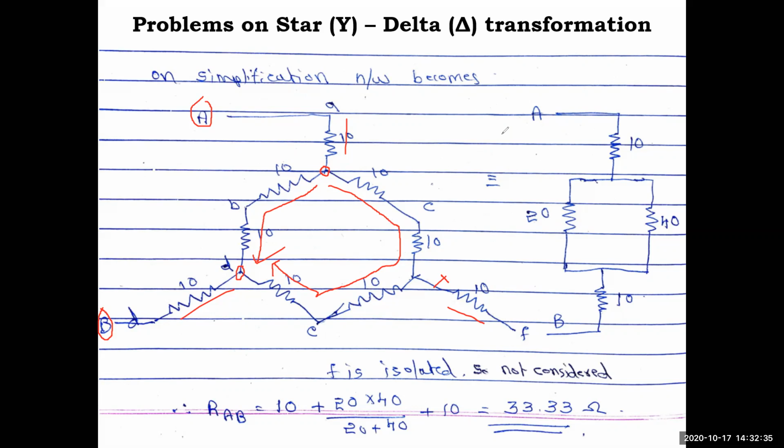So now the equivalent resistance. So 10 ohm, whatever I have copied here, and then these two resistances in series, 10 ohm, 10 ohm, 20 ohm I made, and in this path I have four resistances, so the calculation is 40 ohm I have shown. Okay, and then again I have a 10 ohm resistance here. It is shown. So now do the parallel connection.